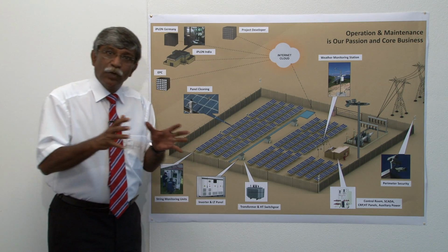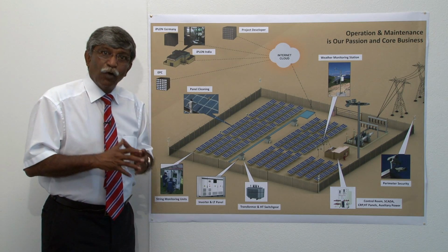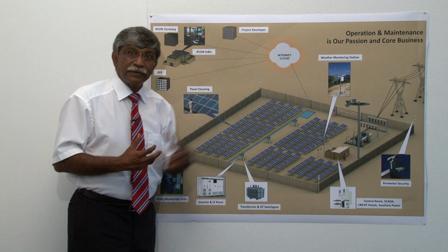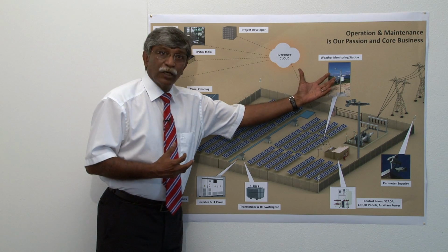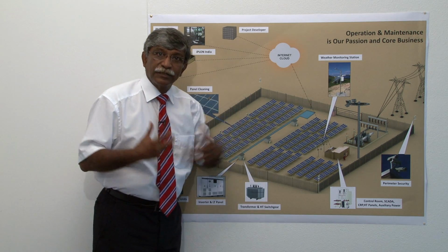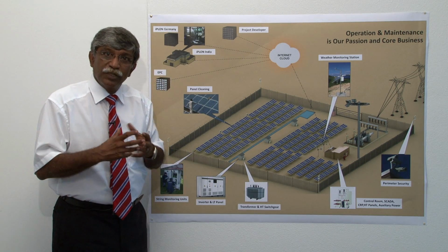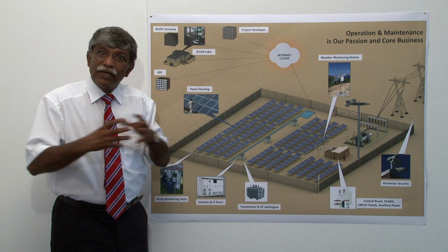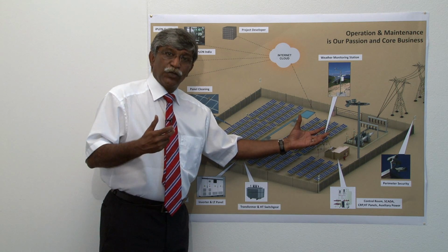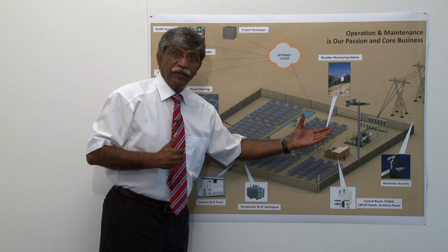Let me take you a bit further into the detail of how energy is being harvested and fed to the grid. Basically, you must have good weather stations, barometers, silicium irradiation sensors, ambient temperature, and module temperature, and with all this information, there are algorithms which tell you how much energy is available at the plant, which could be used to feed into the grid.